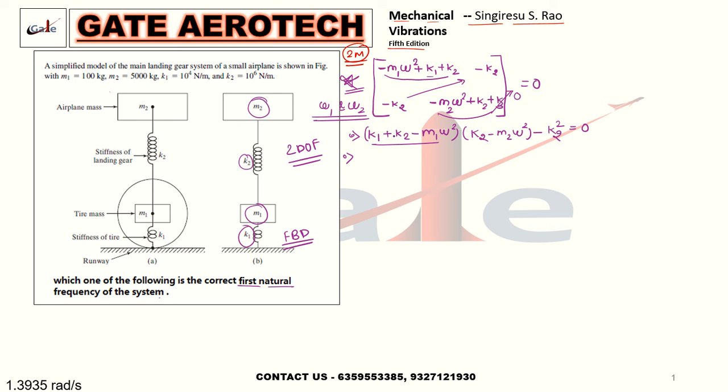I have missed something, but it's okay. Now I will multiply K1 into this, becoming K1 K2, minus K1 M2 omega square, plus K2 square, minus M2 K2 omega square, plus, oh sorry, minus, it will be minus M1 K2 omega square, plus M1 M2 omega power 4, minus K2 square.